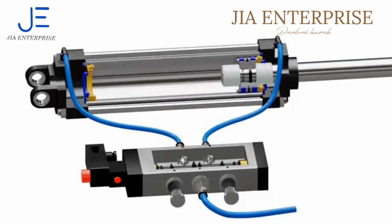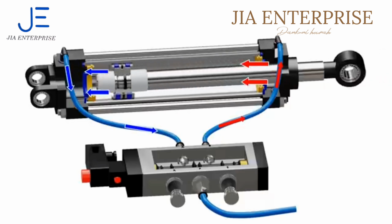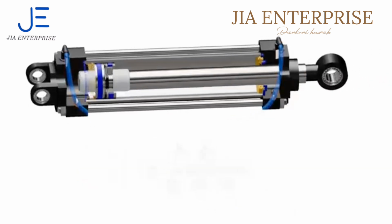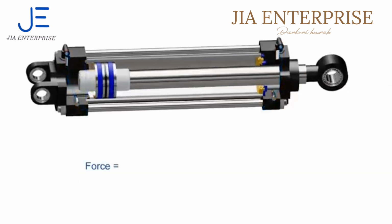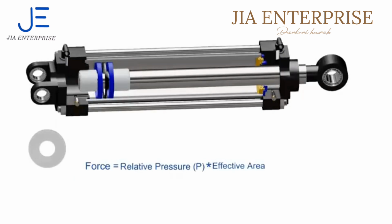During the retraction stroke, the valve directs compressed air to the head end of the cylinder. This causes the piston to return, and air in the other chamber escapes from exhaust port R. The theoretical force of the actuator is the relative pressure on the piston multiplied by the effective area of the piston on which pressure is exerted. Here, the relative pressure is the pressure of supplied air minus the atmospheric pressure.